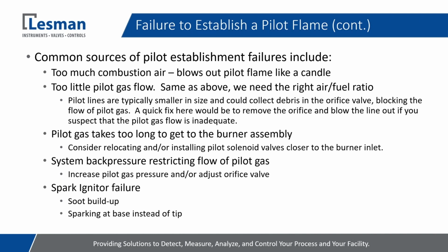It's a very minimal cost for those components. Usually they're less than $50, and if you are having issues with it, there's no way of getting around it or faking it out. You need that igniter to run. So be mindful, and as part of your preventive maintenance, I'd recommend keeping that spark igniter nice and clean.